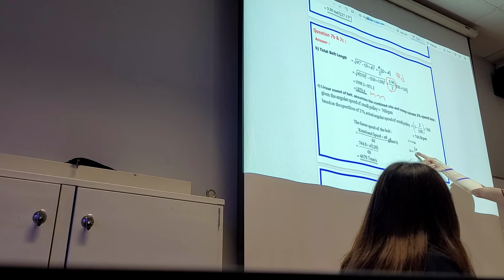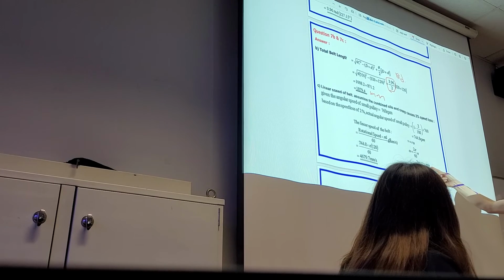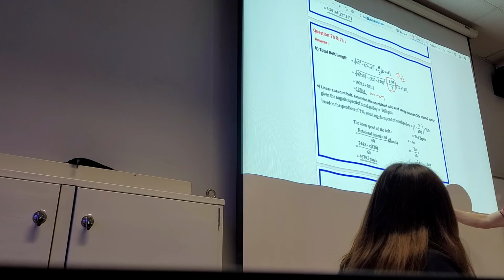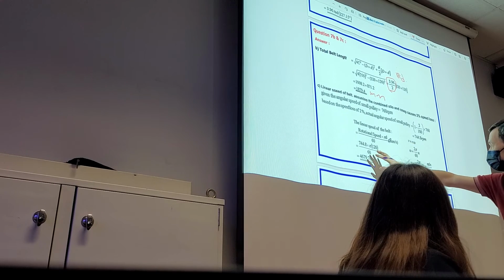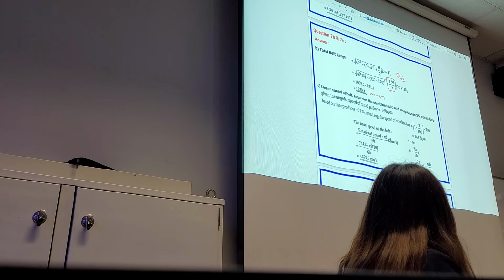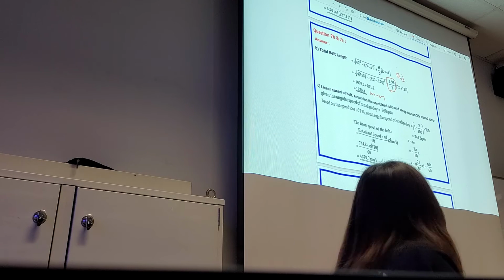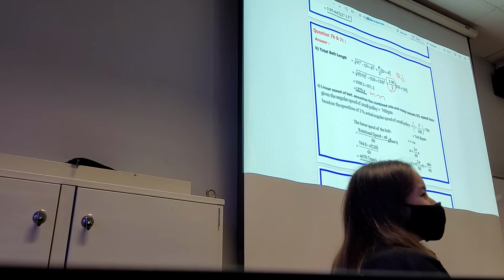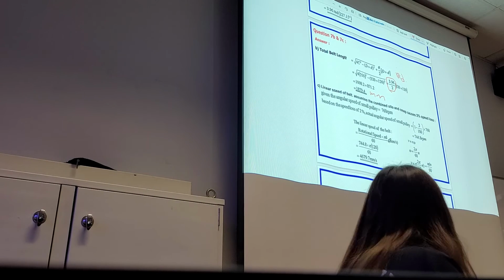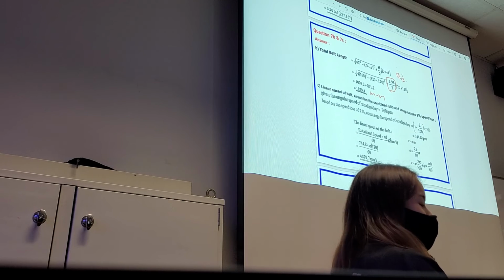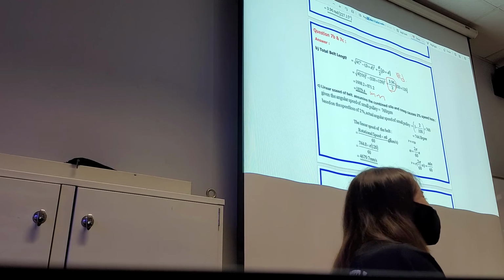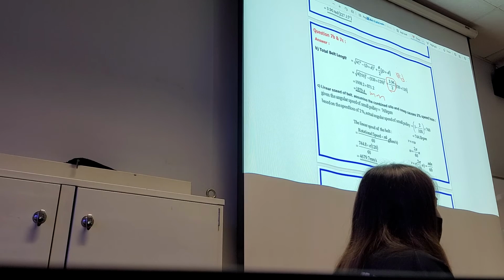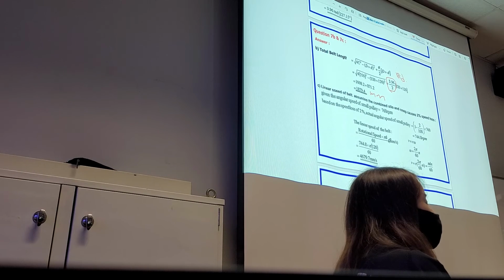Okay, so this formula plugs into here, then you get the answer. Because 2r is basically the diameter. R is the radius. And then using this formula, you can find out the velocity. The velocity is 4,600 millimeters per second. So the belt is traveling pretty fast. In 1 second they can travel 4 meters. Okay, so this is about the calculation of the belt. The gears we will discuss after I come back from the trip.